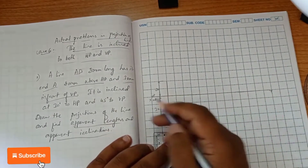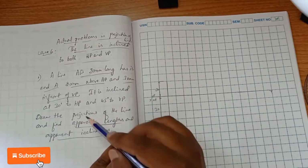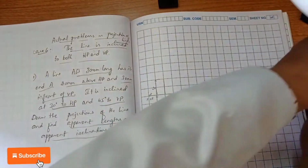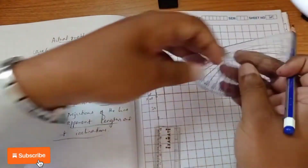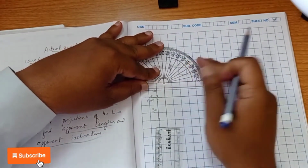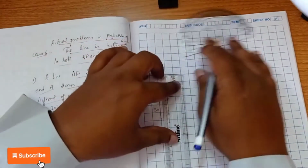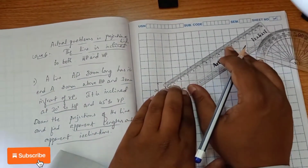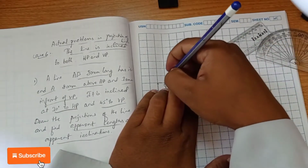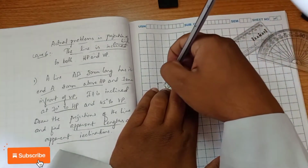Here the length of the line is 80 mm. So AB is nothing but the true length, and you have to find the apparent length. The angles of inclination given are 30 degrees to HP and 45 degrees to VP. First you take the angle of 30 degrees inclination, mark it at 30 degrees and draw a line of length 80 from this point. 80 means 8 centimeters.